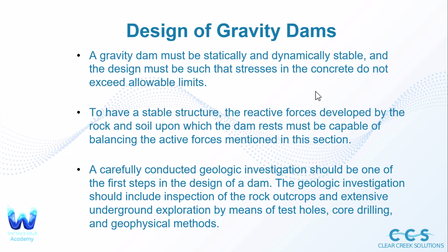A carefully conducted geologic investigation should be one of the first steps in the design of a dam. The geologic investigation should include inspection of the rock outcrops and extensive underground exploration by means of test holes, core drilling, and geophysical methods.